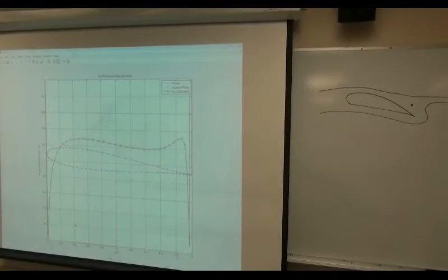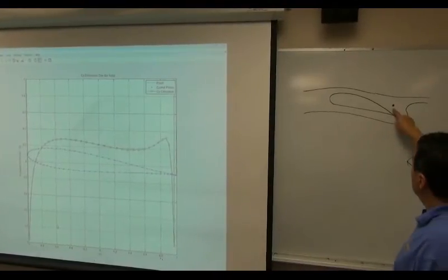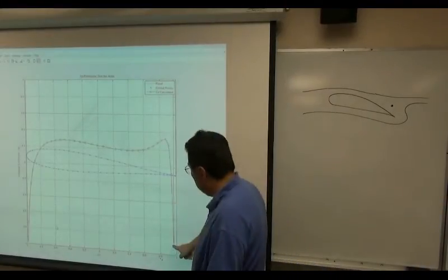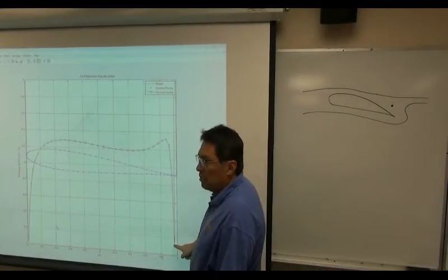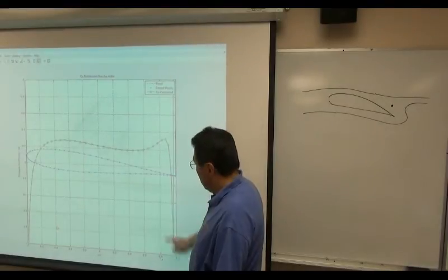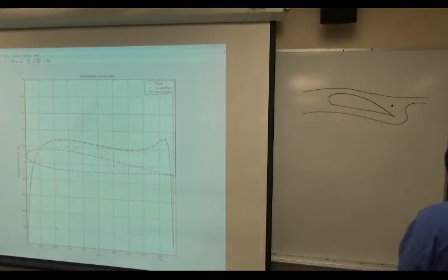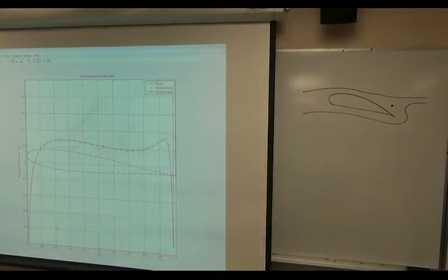All right, good. So if you have a stagnation point formed up here, you're going to have a really high pressure point, because at a stagnation point Cp equals 1. This is not good. Remember in unit B4, is there any way to prevent this kind of thing? Let's go back again.